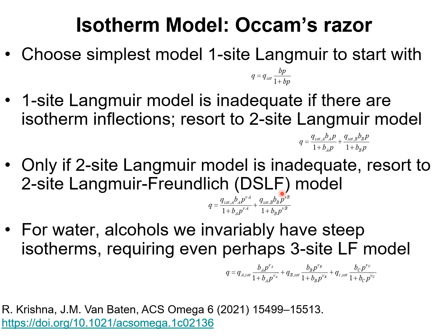Perhaps I may even try the single-site Langmuir-Freundlich model, but I'm usually reluctant, indeed very reluctant, to include the Freundlich exponents mu A and mu B, because inclusion of such exponents leads to problems when we extrapolate the data to lower pressures. This aspect is of particular importance in simulating breakthroughs in fixed bed adsorbers.